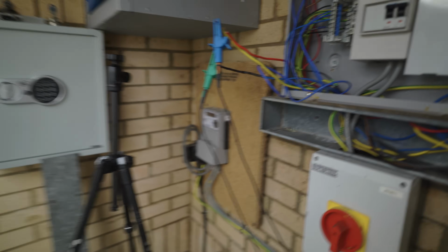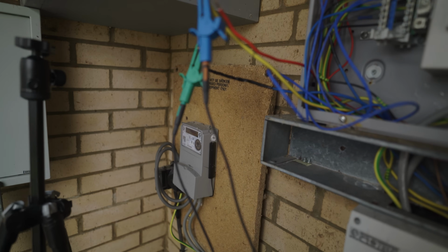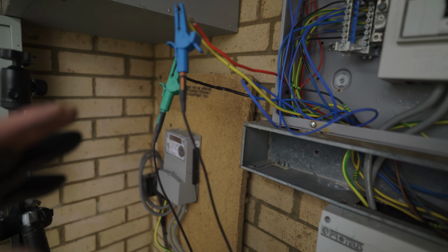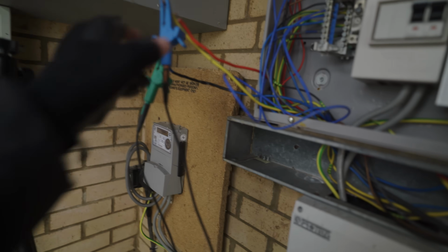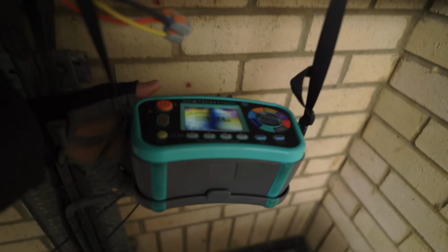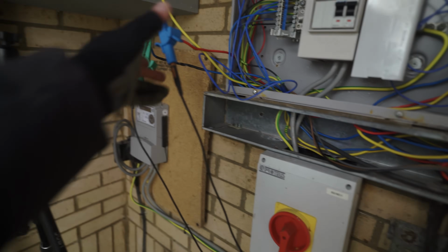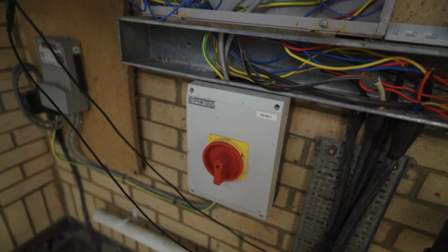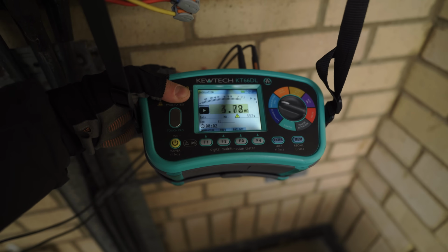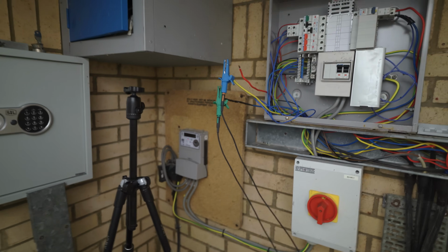So yeah, obviously if I keep connecting them up and that neutral earth becomes a dead short again, then that says to me that there's another issue. But hopefully that was just limited to the one lamppost again. Can't do live and neutral anymore because you'll get that dead short, which is just where the lamps are connected, where the loads are connected. But yeah, we'll connect 3 up at a time, keep testing between neutral and earth, and as long as that stays above 1 megaohm, then I think we'll be sweet.